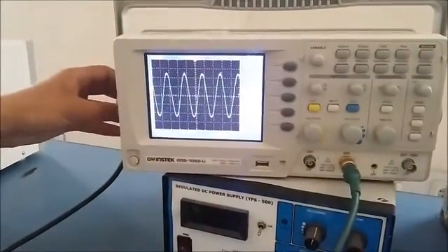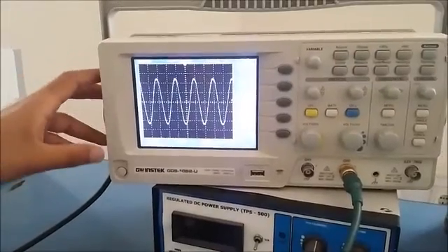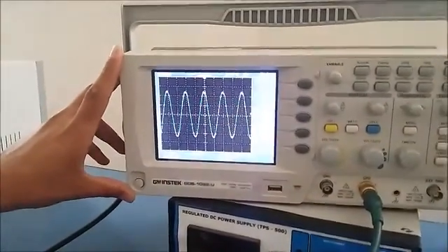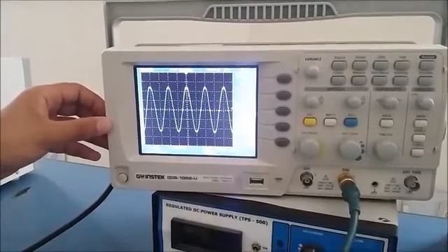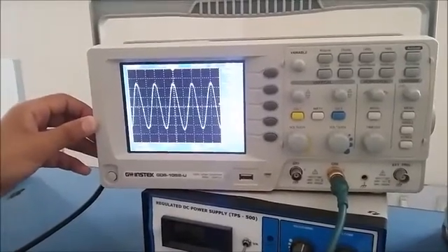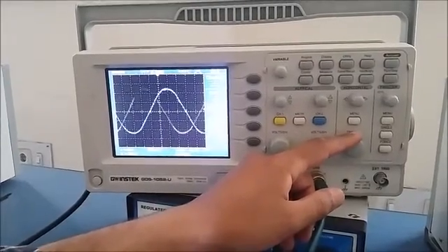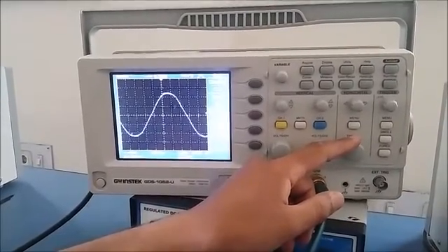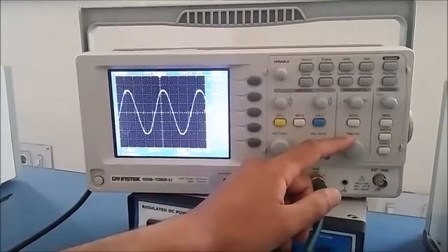Now first we will see the waveform of space vector modulation. Here you can see that this is the line-to-line voltage waveform of our microcontroller filtered at 50 Hz. You can see that our signal consists of least number of harmonics, or we can say that it consists of least value of THD, total harmonic distortion. Waveform resembles close to the sinusoidal, which verifies our space vector modulation implementation.